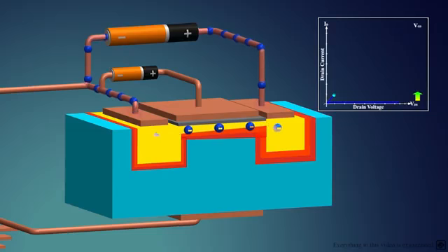but, as the voltage increases, the depletion region between the drain and substrate will increase as they are reverse biased. Also, the channel begins to deplete towards the drain end. This is because the drain is at a positive potential, and negative charges from the channel closest to the drain are being pulled into the drain. This reduces the width of the channel, restricting the flow of charges and reducing the flow of current.